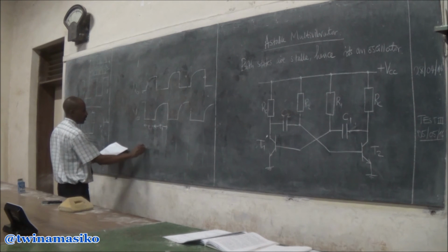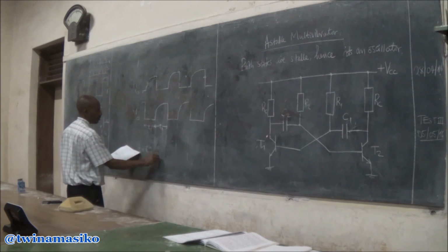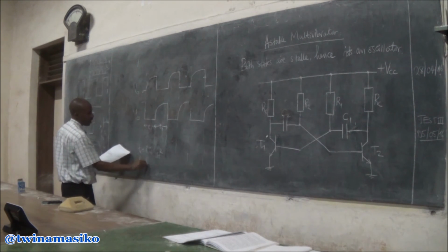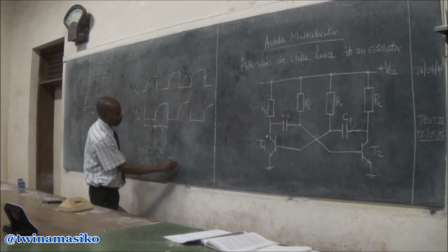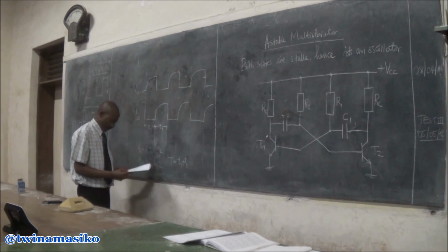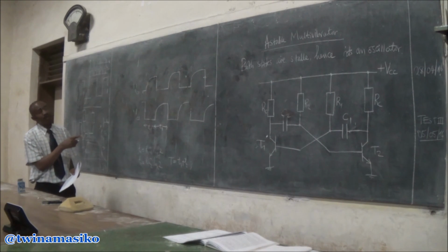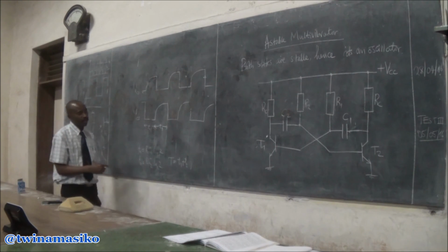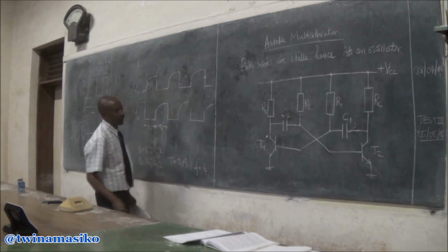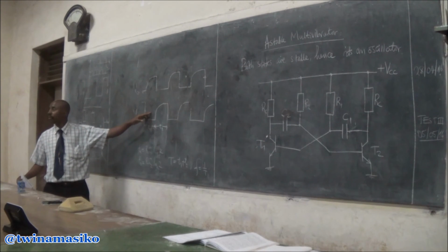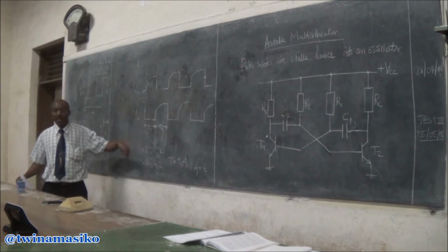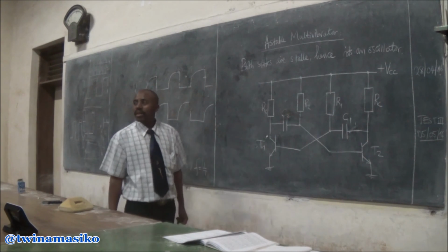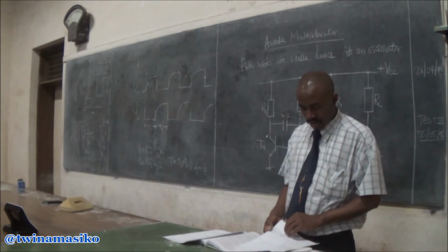So T1 is equal to R1 C1 natural log of 2, and T2 would be R2 C2 natural log of 2. And the period T would be the sum of T1 plus T2, and the frequency of this oscillation will be 1 over T, or 1 over T1 plus T2. So if you were keen on the oscilloscope and looked at the time, using the oscilloscope auto values, and then compared with the frequency shown on the screen, you would be able to get values in a better way.